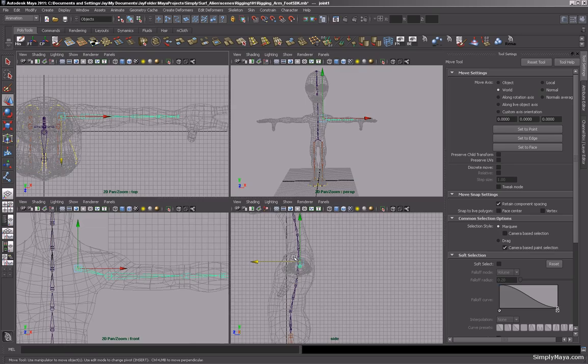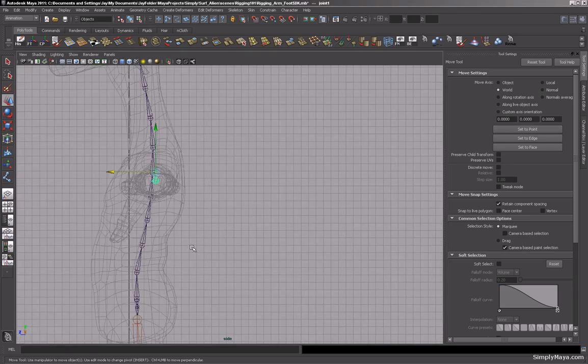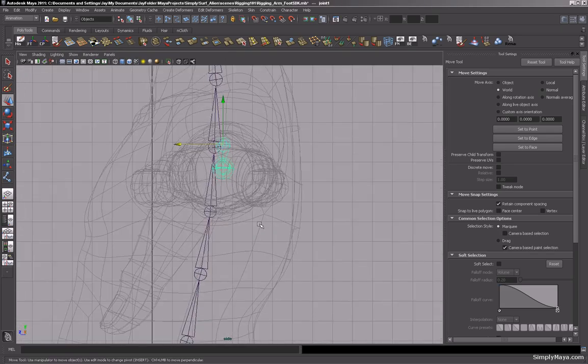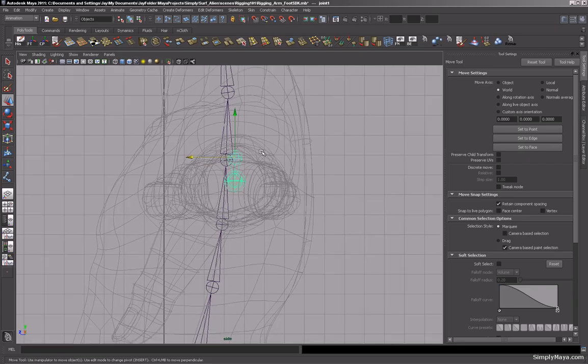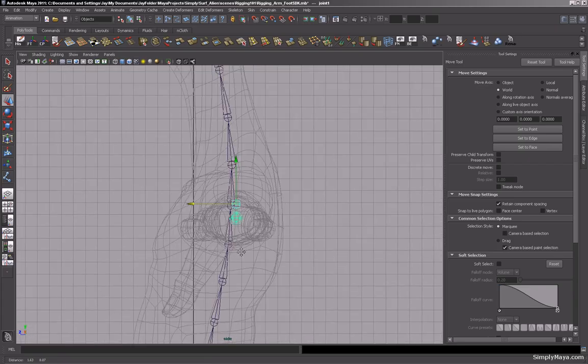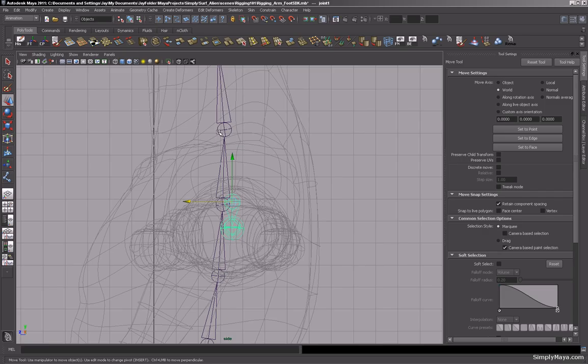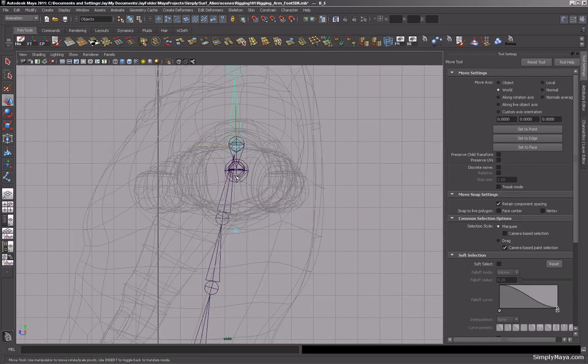Okay, and then in the side view, as you can see here, it's not super great. So I've left the rotations, as I said before, I've left everything where we've drawn them, because I knew we may have to edit some bits and pieces. So again, with the insert key selected, just sort of move your joints around until you're sort of happy with their orientation, and we should be okay. So I'm going to leave that there.